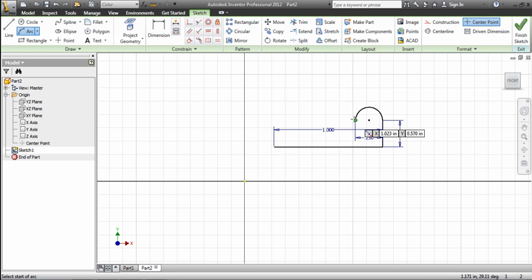And I'm going to click on the end of the arc here again, and I'm just going to come down a little ways. Don't worry too much about the angle, but just come out around 0.5 inches and come down about, let's just say, 165 degrees, somewhere around there. Don't worry if it's not exactly right. Click, and I'm going to curve this down to about 0.338, somewhere in the 0.3 range, an arc like that.